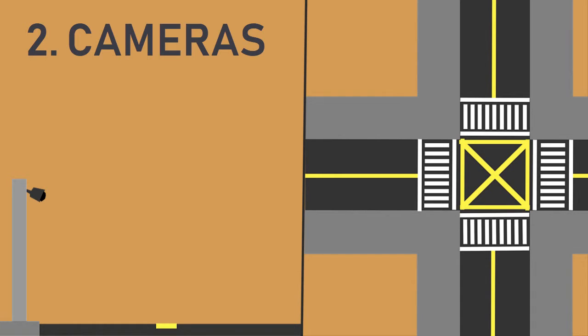Cameras, meanwhile, may be placed on the intersections of interest, and through the video produced, the vehicles that turn in the intersections may be identified through vehicle recognition software. Just knowing how many cars pass through one section of a road is insufficient, so you would also have to know where they're going. Cameras may be used to measure turns and match the amount of vehicles that pass through a road segment.